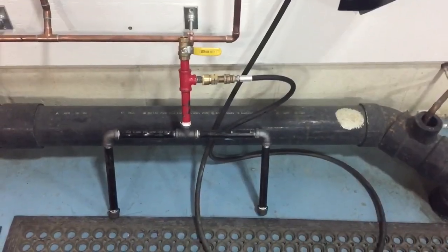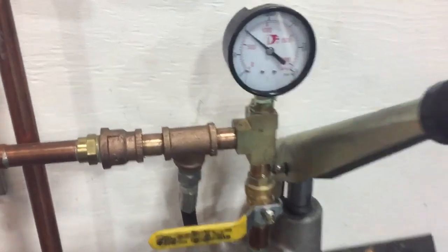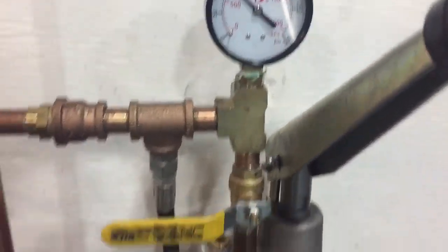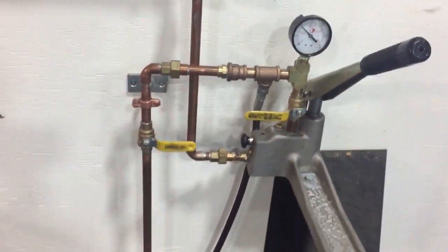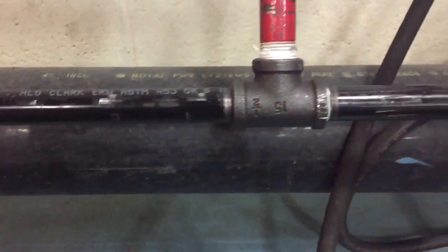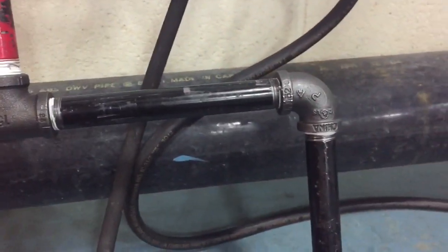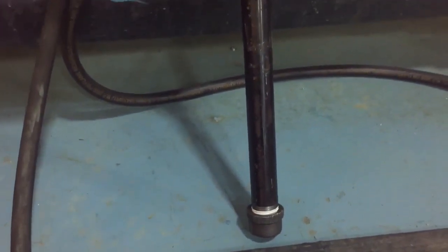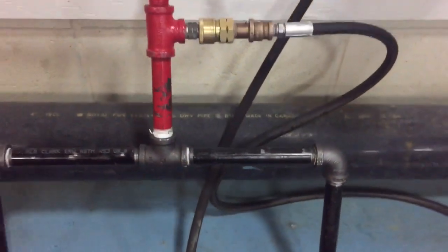Okay, so I have this hooked up to our water lines here and pumped it up with our pump, and it's sitting here at 100 psi, and I've blocked it all in now, and we're just waiting to see if the pressure is dropping. And it's been there for about a minute or so, so should be no leaks. I don't see any water dripping out of any of the fittings, so looks like everything's good. So we pressure tested this for 100 psi.